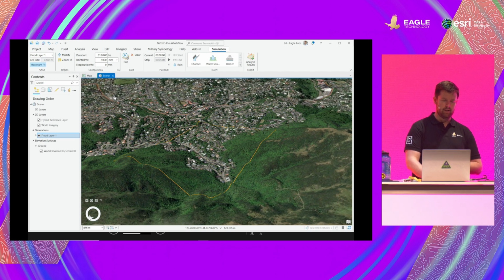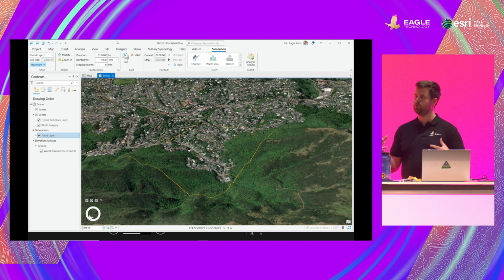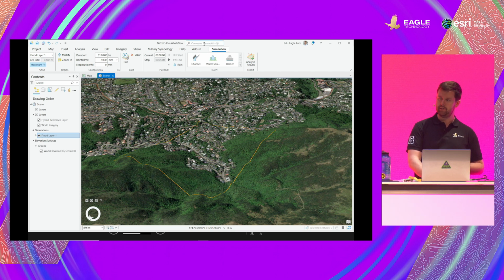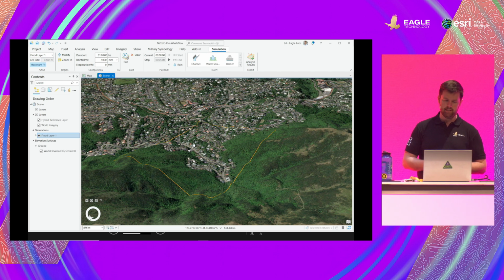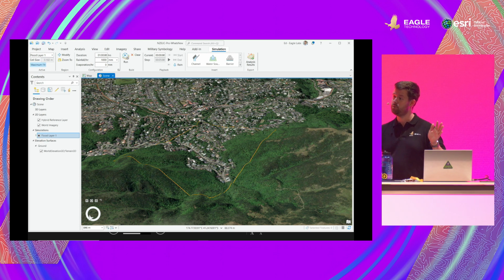And so the flood simulation toolbox, it is launched directly from the top pane that you see here in one of the settings. And how it works is a three-step method. You draw your area of interest for where you're going to run your simulation. You then set some variables against it. So how much rain do I want to fall from the sky over what time period?